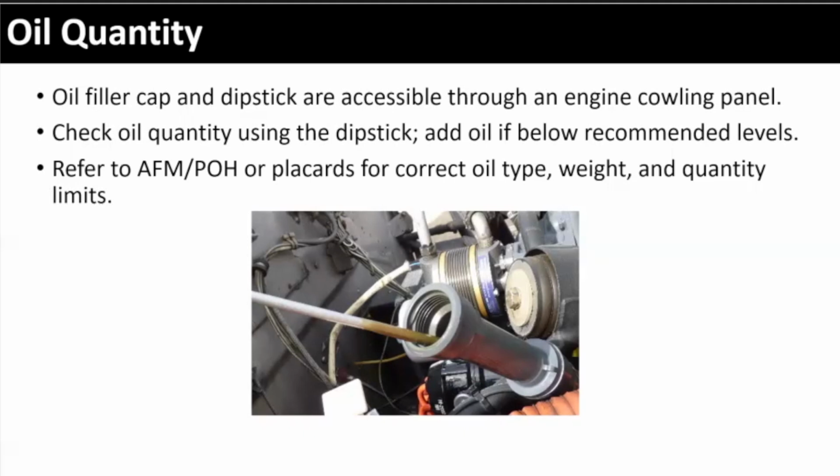Yep, every 50 hours of flight they do an oil change. Not only do they change it, they test the oil. They're looking for sediment, they're looking for shavings. They have different tools and standards to see: is the oil doing its job, or is the engine deteriorating?